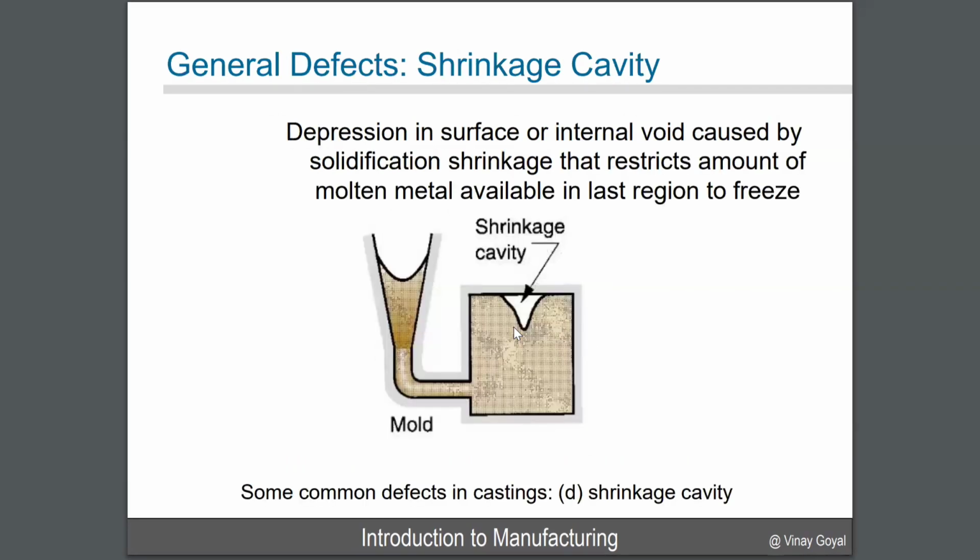Shrinkage cavity. I can also look at that and see, okay, is that going to be a detriment to the performance of my application? If the answer is no, no problem. If it's a detriment, then I have to find a solution. One solution is to machine it off, and it's going to have a little groove. If I did that, is that groove a problem? If I can't have that groove, I have to think of other solutions, such as filling that out with another approach, like spraying metal or something.